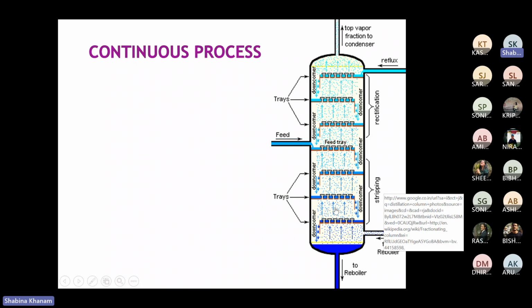Actually it is not absorption, it is desorption. Absorption, you understand, is from gas phase to liquid, and the reverse of that would be desorption, which we also call stripping. Because in this case the components which are available in the liquid, the light components, would be transferred to the vapor.